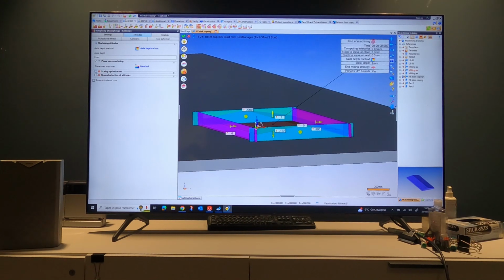Yeah, okay. So that's why I like to do this, because especially you will see in the future you will do a lot of roughing for the guys and finish by hand. So if you do the flat level at the correct position for them, it's better. Yeah. That must be it. When I was doing surfacing using the program, I could specify 5 millimeter steps, but sometimes the last final pass would only be a mil or two, because it was coming down to the height that I had specified.